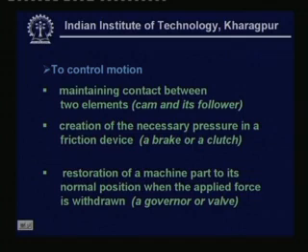Whenever you have to control the speed, which is going on increasing or decreasing, a governor system is used which controls the rotation of the turbine wheels, and thus the flow through the turbine vanes by the governor mechanism, which controls a series of vanes for inlet water impingement, and that is also controlled by springs.